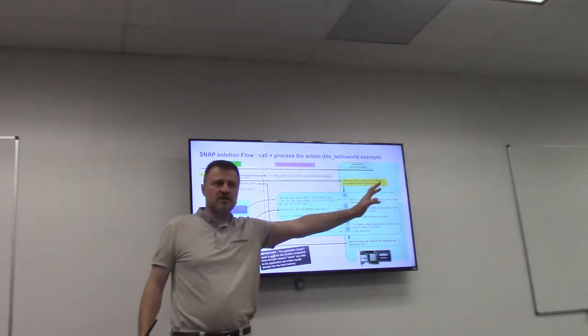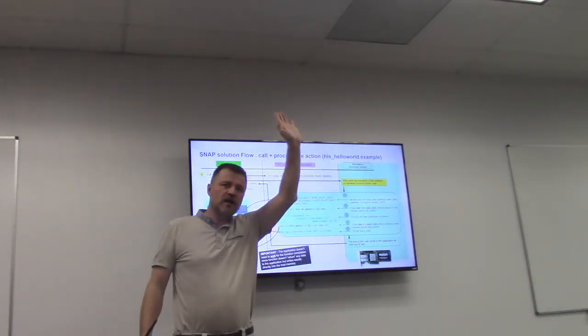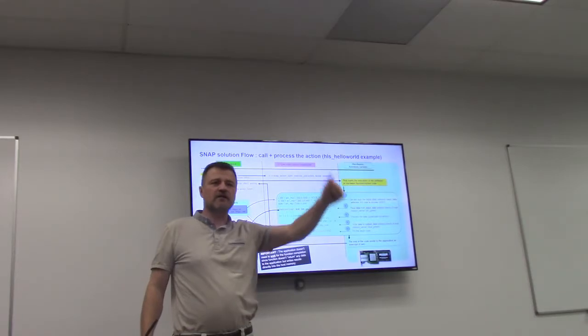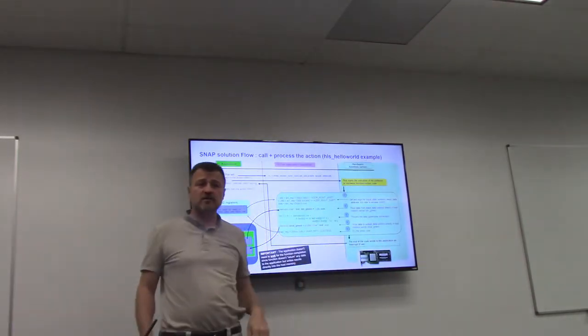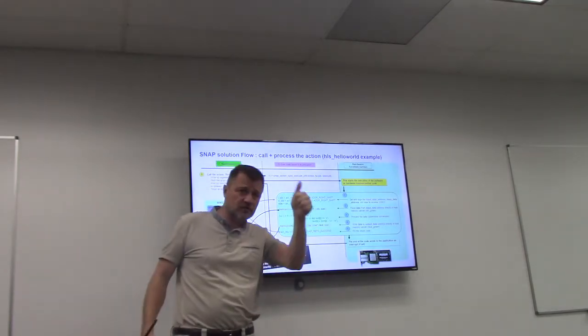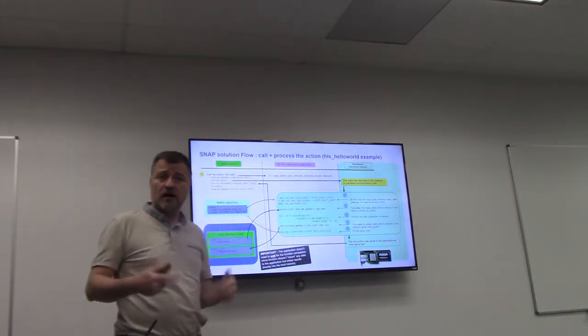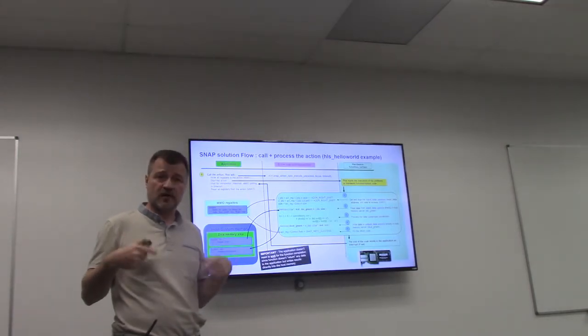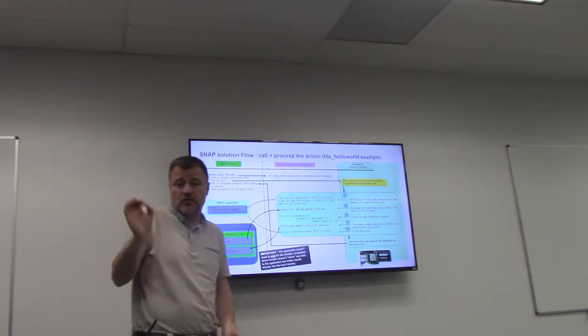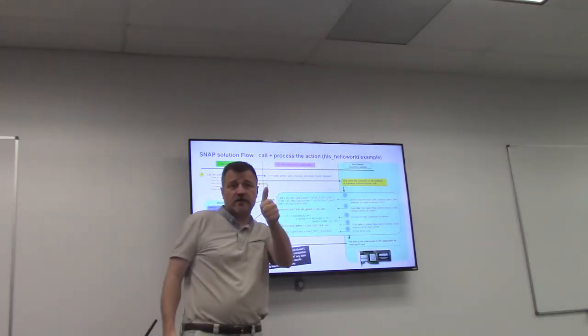At this time, the FPGA can say, I'm finished. It can generate an interrupt. It can write a bit into the register section saying, I'm finished, but I still have some more job to do. I finished the first part. But you can continue, like I'm waiting for a new video to come. I'm ready to uncompress, but no video for the moment. So you say 0, no video, and first one is ready.